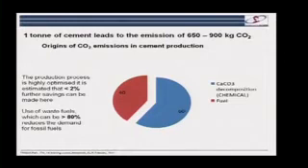Furthermore, because of the flexibility of this cement kiln, you can actually use a lot of waste fuels, and now typically in state-of-the-art plants, about 80% of the fuel you need will come from waste. And these wastes can be very varied and diverse, things like car tires, offcuts from making sofas and things like this, animal bones, just about everything can be put back into a cement plant and its calorific value used.